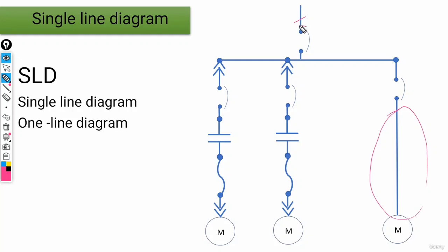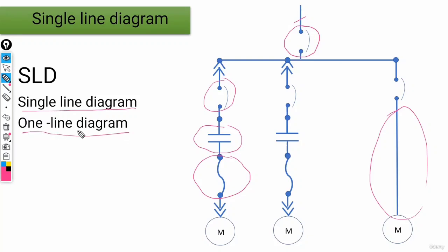And by the way, guys, we actually got several electrical symbols as well. Like, for example, this symbol up here actually represents a breaker, a switch, okay? And also the same goes for this symbol. Then we have a symbol for the contactor, or even a symbol for protective elements, as you can see here. So guys, what we can get from all of this is the fact that in SLDs, or single line diagrams, we actually have some specific electrical symbols, all right? And also, no matter how many lines we actually have, they would all be displayed as single lines.